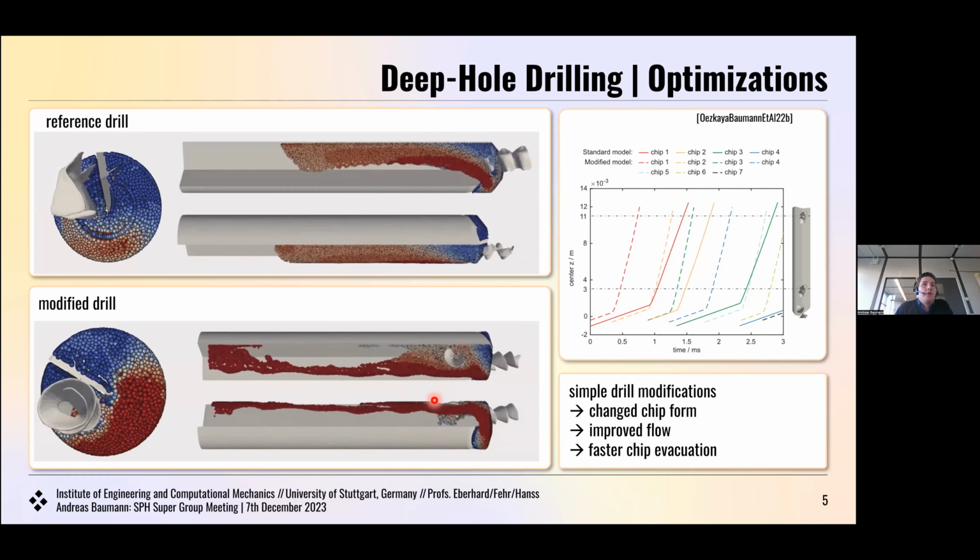So we see that these minimal second fluids have only a minimal influence on the fluid flow. The main of the fluid flow still flows the regular way to remove the chips, which is, of course, one of the goals as well. However, the second flow along the cutting edge is not sufficient to improve the cooling of the cutting edge significantly. It would require a significantly larger drainage along this way to increase this furthermore. However, it comes back that the structural strength wouldn't then be guaranteed.